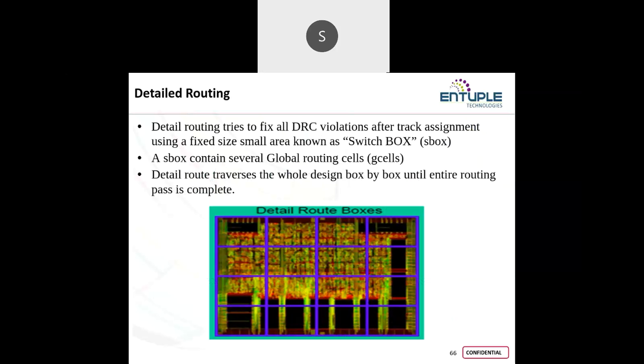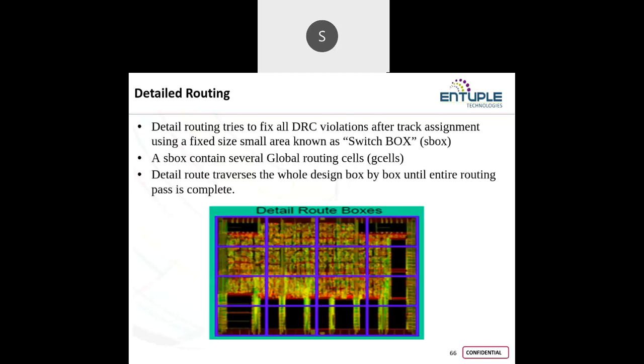In the global routing, it will also allocate the routing resources used for the connection. Track assignment is taken care of by assigning the tracks with horizontal or vertical partitions, and once again we will be checking for the rerouting of the overlapped wires.